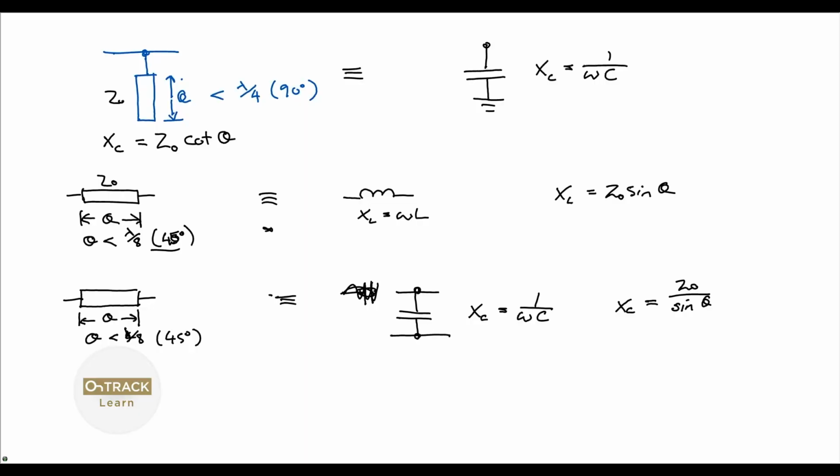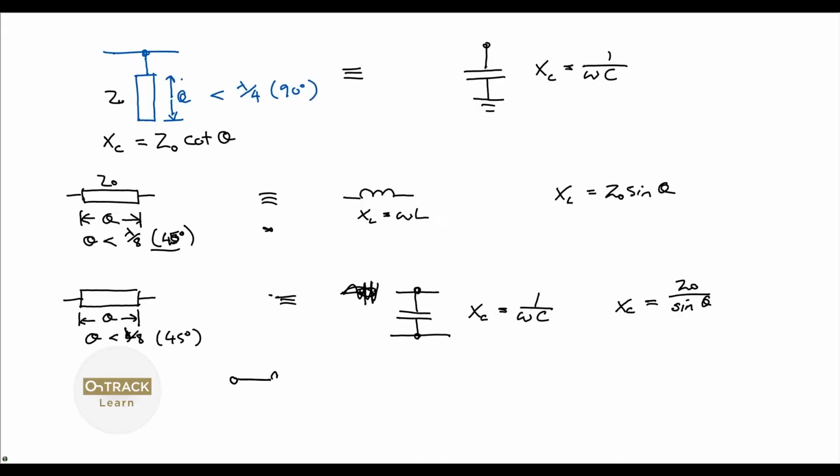So if you have a longer trace, you could work out the equivalent piecemeal by dividing it up into eighth wavelength sections and using the transform, and then putting all those capacitors in parallel and inductances. And of course, that's what you get with a transmission line. If you look at any normal lumped element view of transmission lines in any electrical technology textbook, you'll see a transmission line is usually first presented like a bunch of discrete L's.